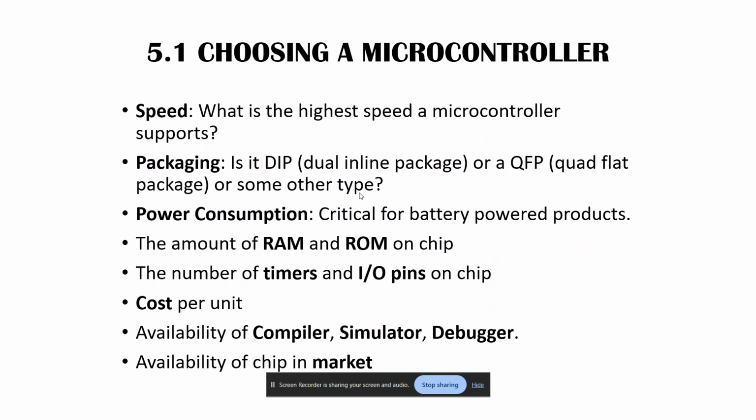Now, one of the most important things of today's lecture. You can say it's one of the most important topics of this lecture: choosing the right microcontroller. It's very important to choose the right microcontroller, whether it's speed, packaging, power consumption, RAM, ROM, timer, input output, cost, compiling, simulating, debugging, or availability in the market.